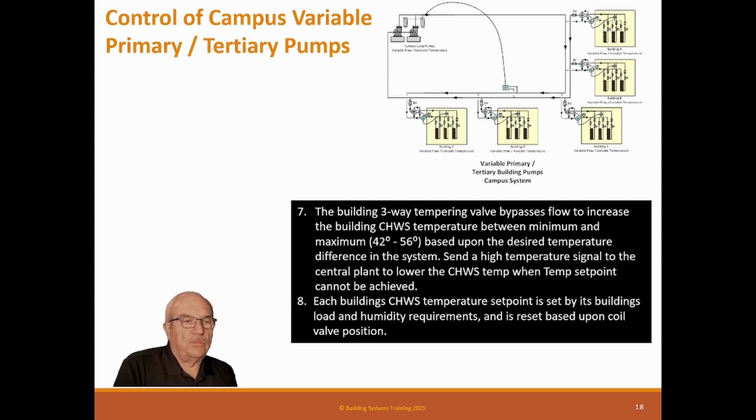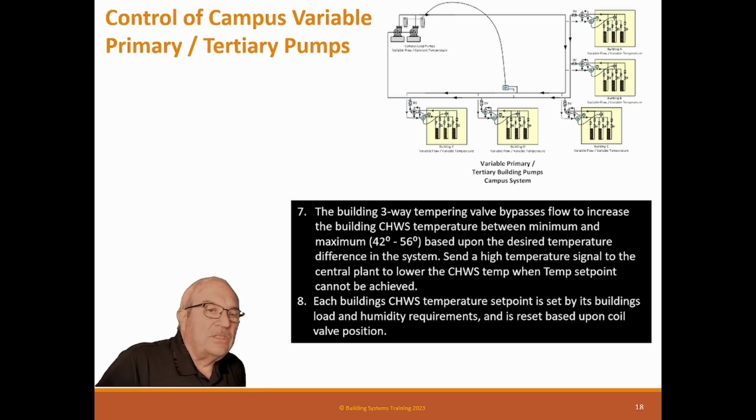Each building chill water supply temperature set point is set by the building load and humidity requirements, and it is reset based upon the coil valve position, just like other systems.